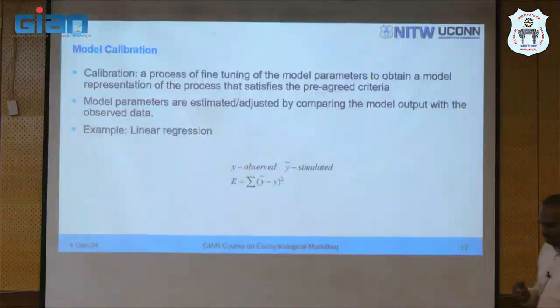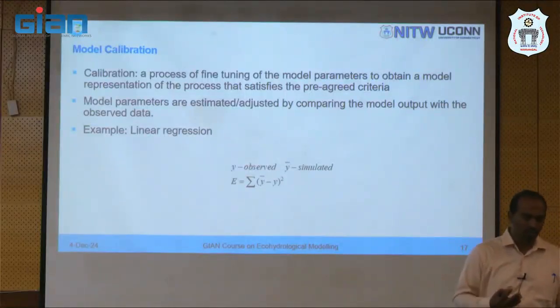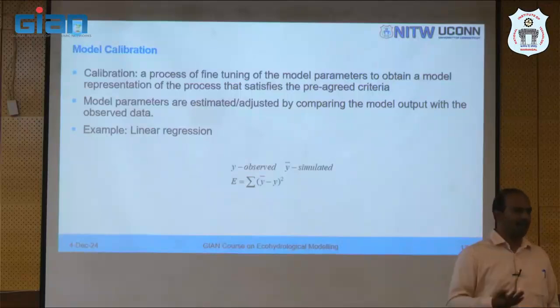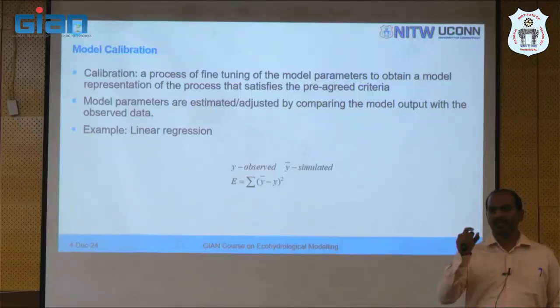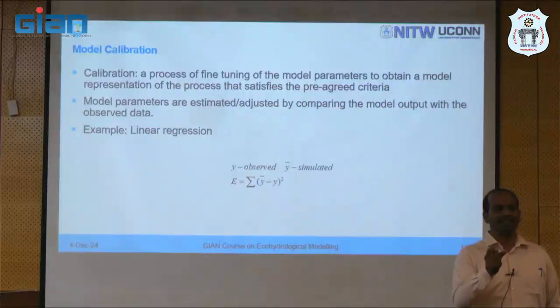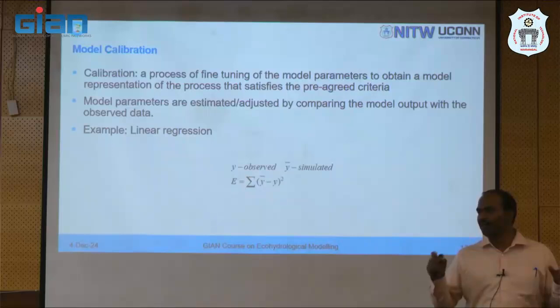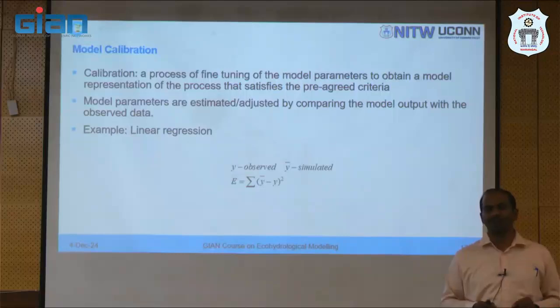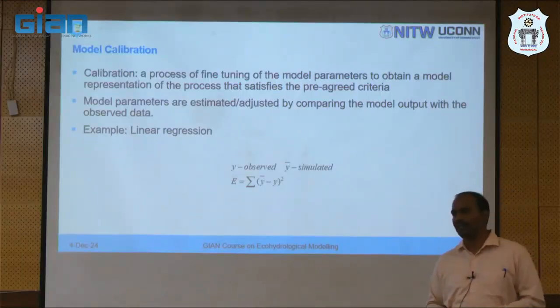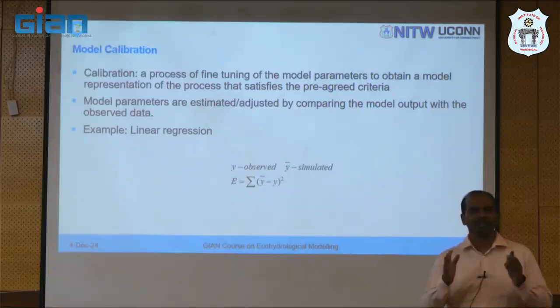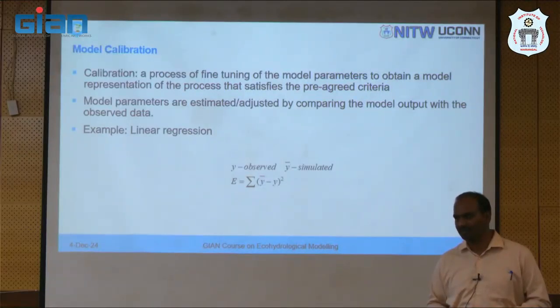Now in this process, what we all do, in some cases even I do that, is we tweak the parameter so much that it does not represent the process in the field anymore. We tweak the curve number, let us say between 50 to 100, and we have known that the curve number should lie around 65, but in the optimization process it becomes 85 or 90, that means you are completely changing the land use or soil, right?